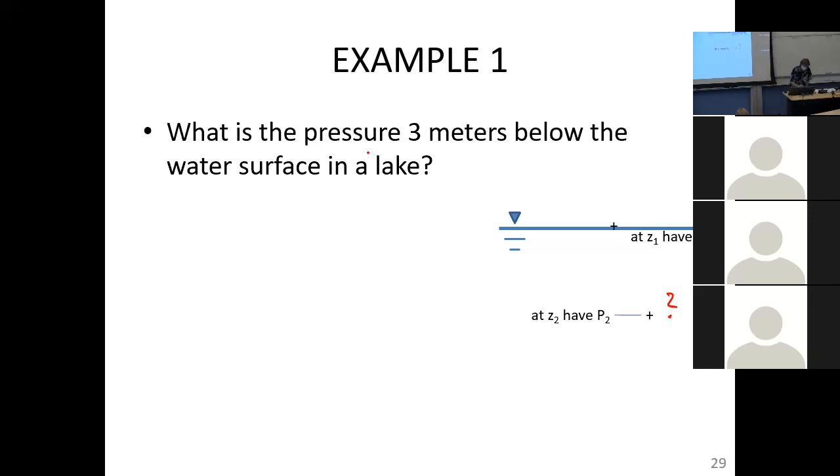However, in this problem, what is that telling you as far as the 5 variables? Specific weight, right? So you know the specific weight. Now you know that density and specific weight are temperature varying. No temperature is given in this problem. My guidance to you in the past, and will continue to be, if in this course a temperature is not given, assume it is at room temperature, 70 degrees Fahrenheit, 20 degrees C.